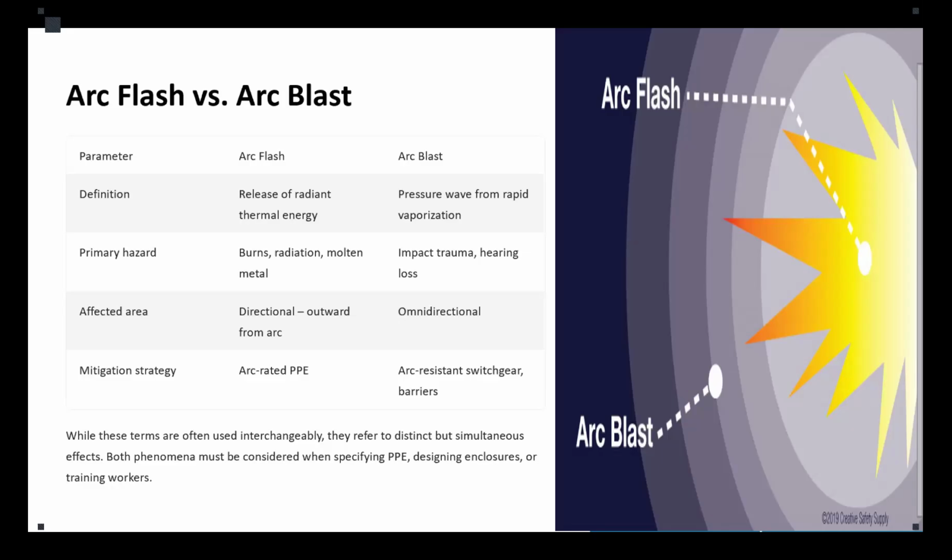Now, on the other hand, arc blast refers to the pressure wave caused by the rapid vaporization of the conductors and the superheating of the surrounding air. So it's a shock wave. Okay. It is driven by the mechanical expansion of the plasma and the metal vapor, not thermal radiation.